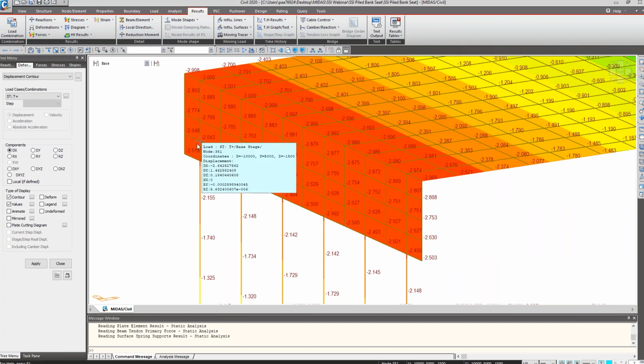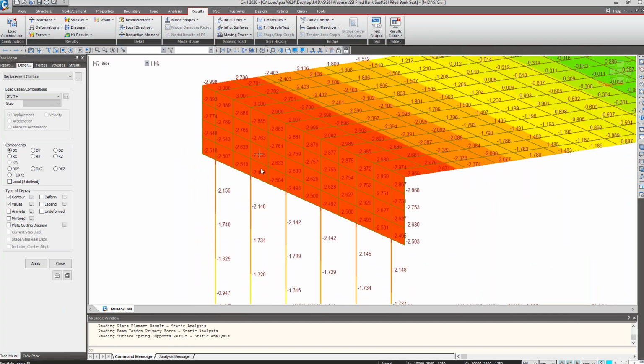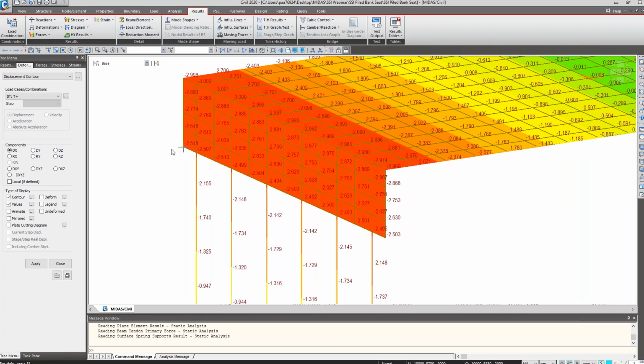So as I said, it's not black and white, but probably making this assumption and seeing that there is not a huge variation between the displacement that you're getting and using the maximum displacement that you're getting on the abutment to extract the K-star, what you're doing is basically assuming an upper bound for the K-star.